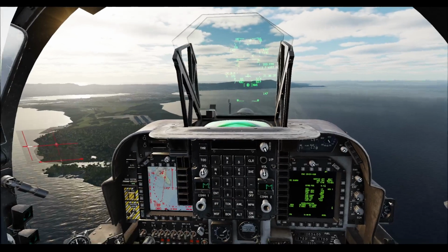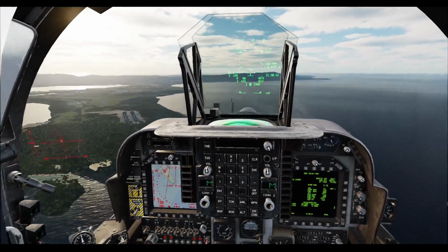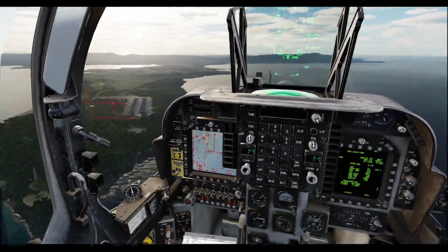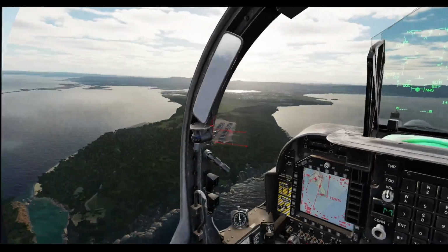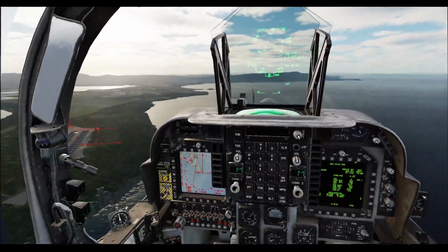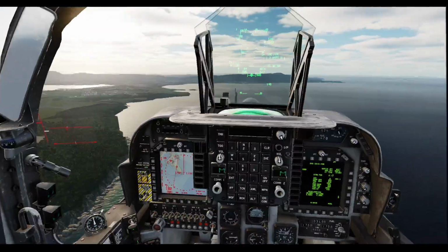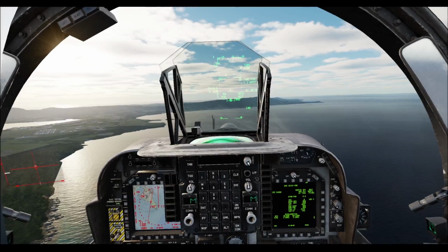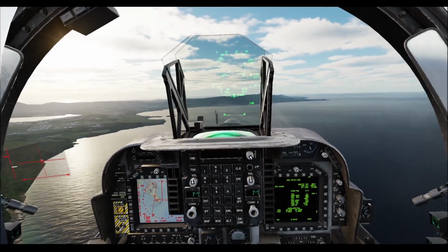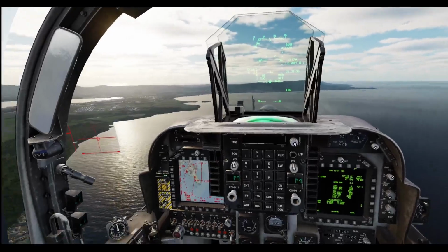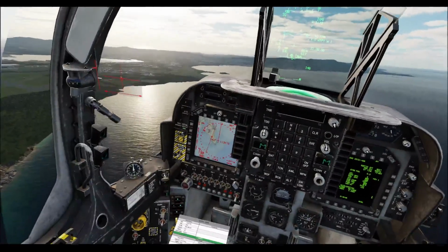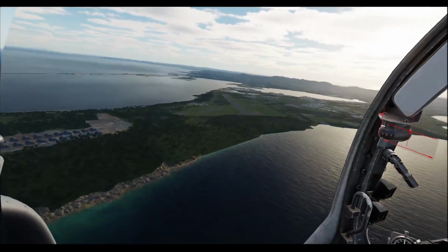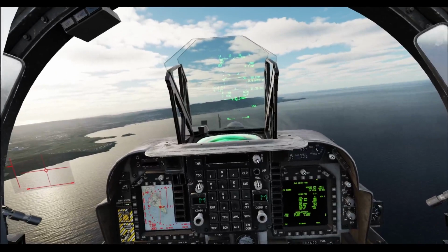So I'm going to bring the nozzles back to 60. Don't touch the power, bring the nose down to counteract the balloon. Now adjust the power and trim. And we're at 1 nautical mile, delta distance, we're not quite abeam yet. Adjusting the power to maintain on speed, straight and level. And we're going to come parallel, 0.9, perfect. And there we are, we're abeam, so at 15 we're going to go up to 25.